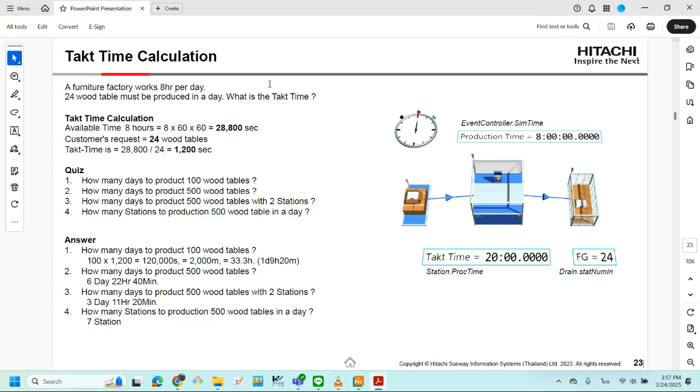I need a takt time in the one line. In that example, it was very easy. It's just one line, one piece, and one part type fed to your process. You calculate this one: the cycle time of just one station and just one part type.